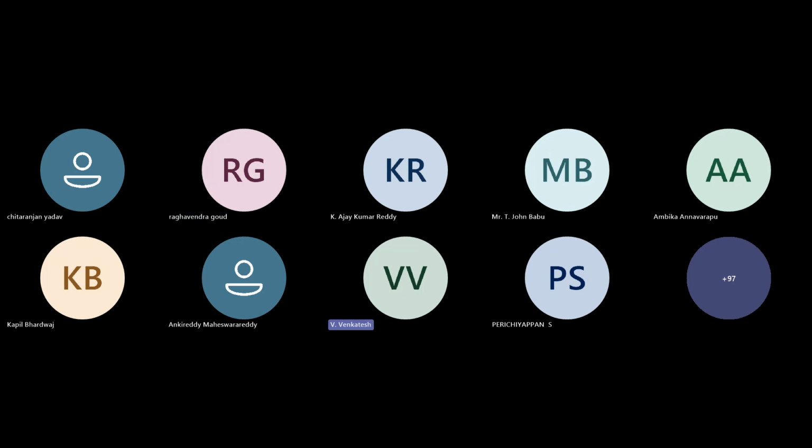So for load-bearing applications, you should use metal implants. Okay. Means we can make use of this machine for non-load bearing implants. Yes, exactly. You can use it for polymer or polymer composite powders only, not the metal powders or ceramic powders.